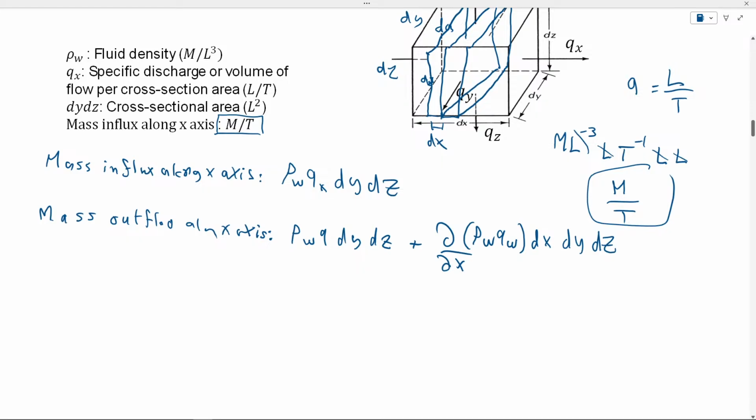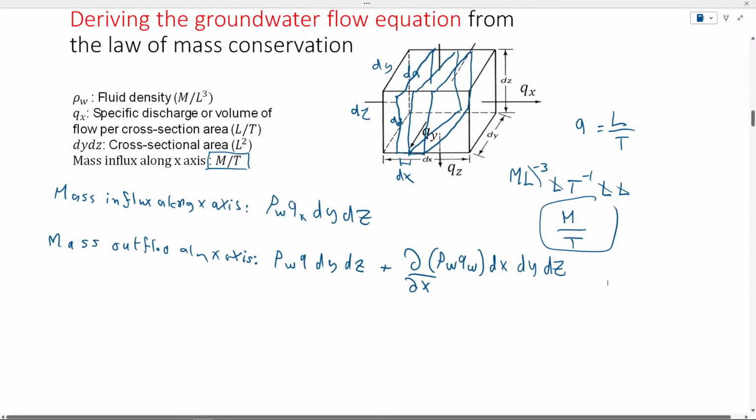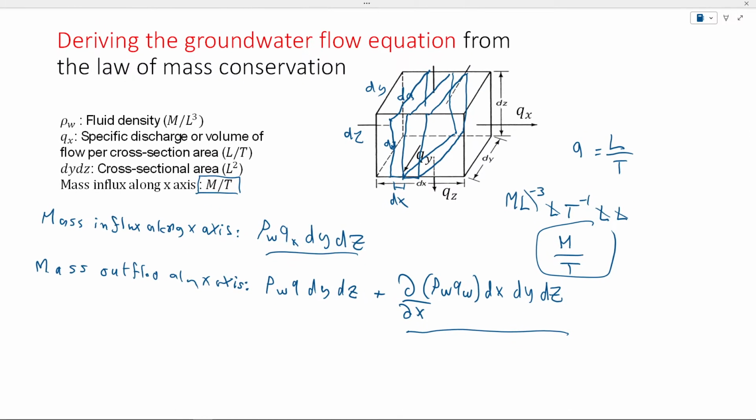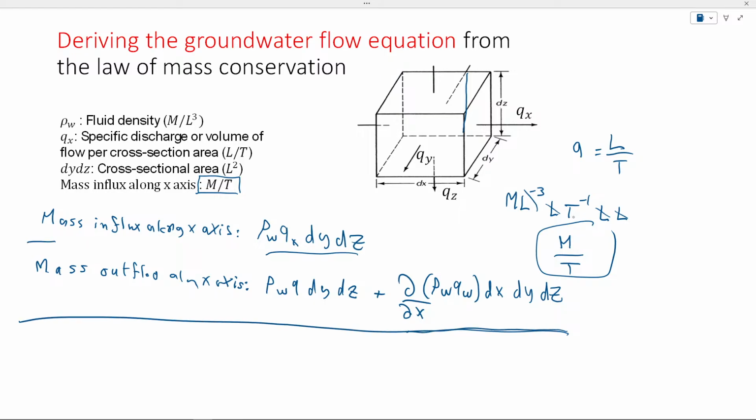So basically, I got this equation here. That is basically my volume integral, like this. That basically my volume integral, like what is it changing inside this volume here. Yeah. Let me delete. So basically, that is what is changing inside my volume here. Okay. So if we subtracted this guy from this guy, yeah, the mass inflow from the mass outflow, so basically this guy will go away with this guy, and I will get something like this.